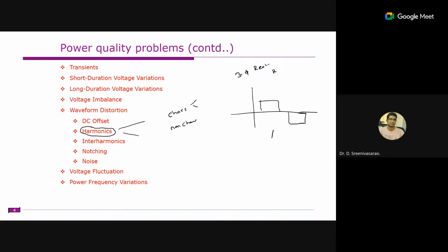If you decompose this into Fourier components, you will usually get harmonics like the fifth, 7th, 11th, 13th. So the harmonic order will be 6k plus or minus 1 on the AC current side. Similarly, on the DC side, we have 6k order harmonics, like the 6th, 12th, and 18th order harmonics in the DC side output voltage.